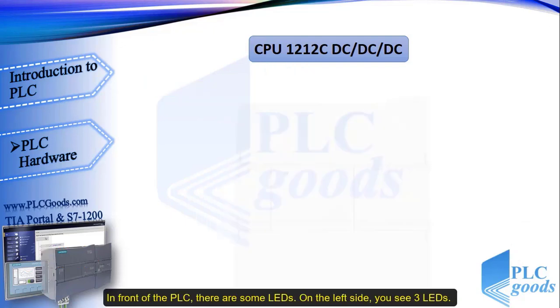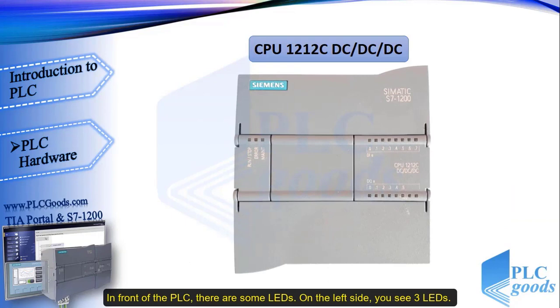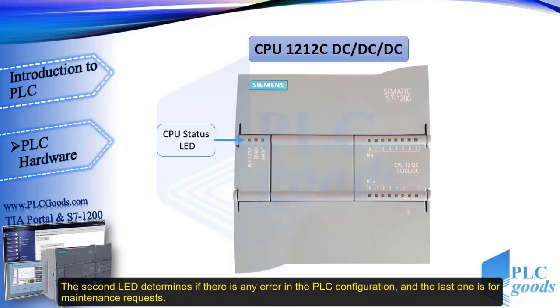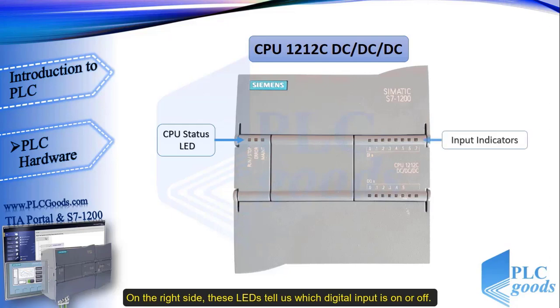In front of the PLC, there are some LEDs. On the left side, you see 3 LEDs. The first LED shows whether the CPU is running or if it is on stop mode. The second LED determines if there is any error in the PLC configuration, and the last one is for maintenance requests. On the right side, these LEDs tell us which digital input is on or off.